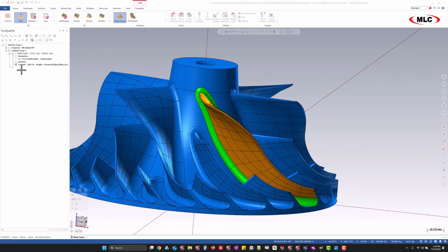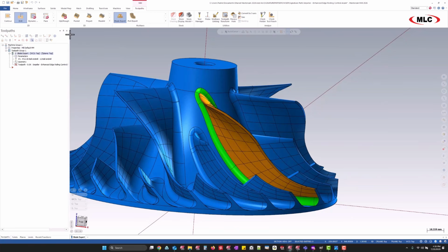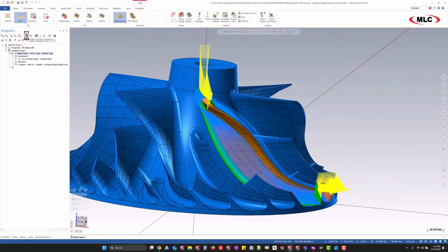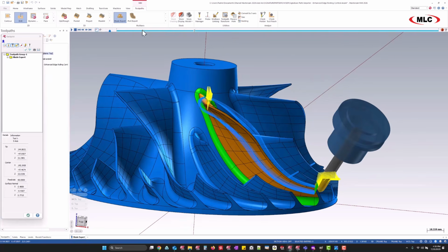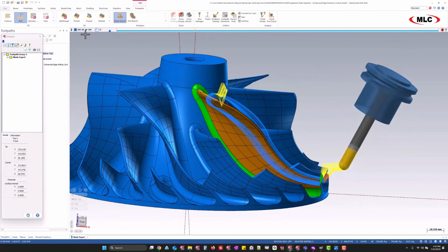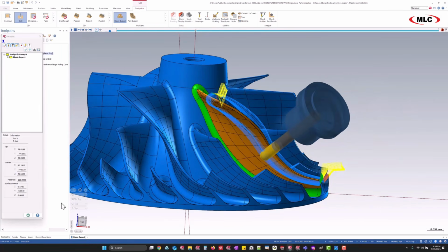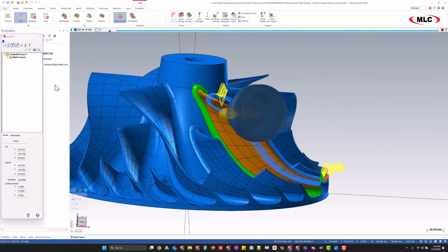So then as we generate this toolpath and take a look at our back plot, I'll go ahead and just kind of forward through part of this. Notice how as it's coming in, we have our feed rate set to 120. And as it's approaching around that radius there, and it's just starting to roll around, it changes to 60.